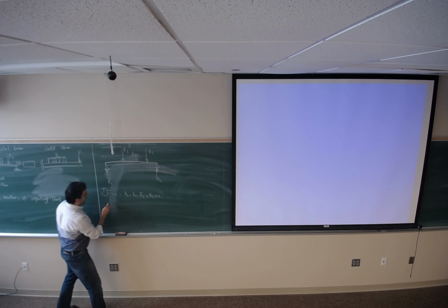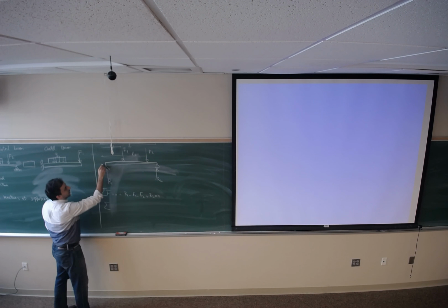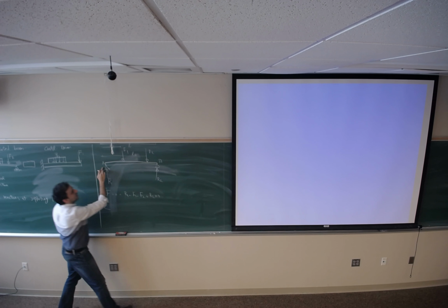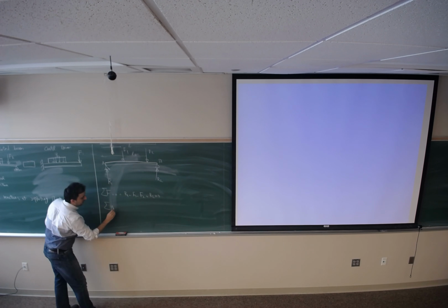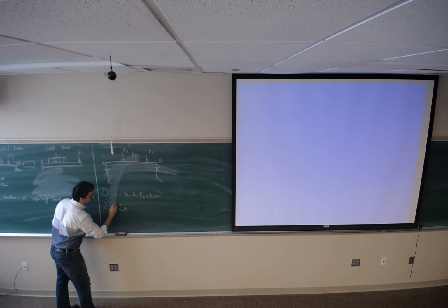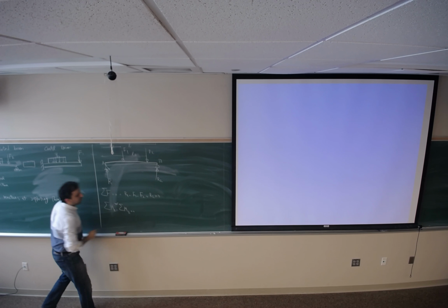This is the similar thing that you should do for any other beams, including cantilever or simple support. The second equation that I can write, if this is point A and this is point B, you can write either bending moment at point A or bending moment at point B equals to 0. Just use one of these equations.